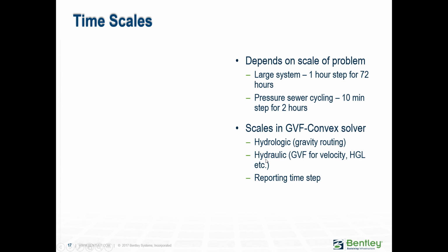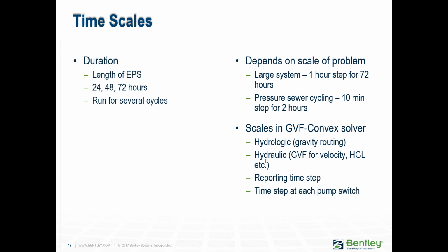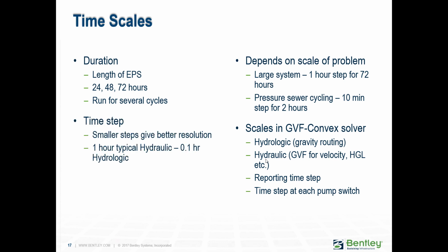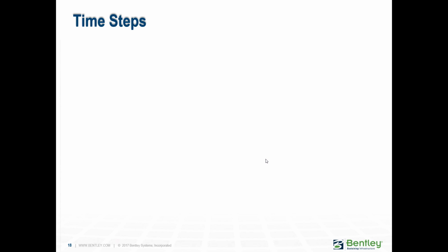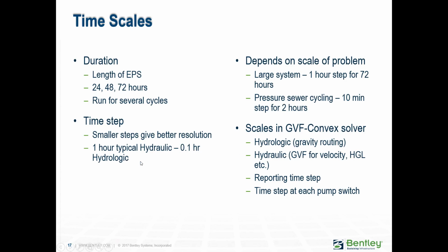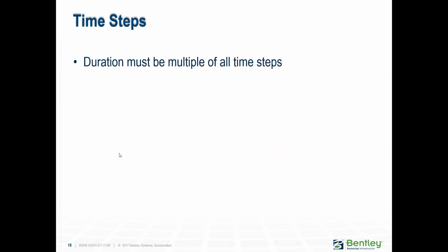It might take a few more seconds to compute, but then you won't see any gaps. Again, the duration could be 24, 48, 72, or more. And typically, we run 1-hour hydraulic time steps, 0.1 hydrologic time steps.